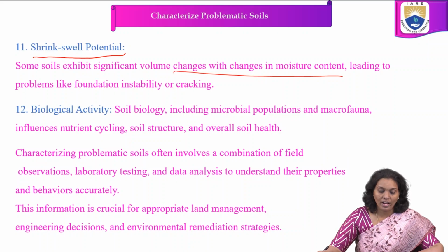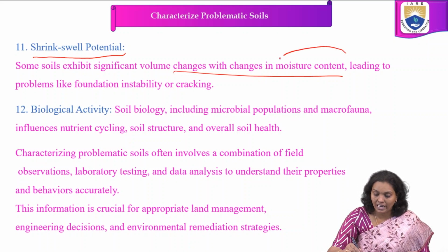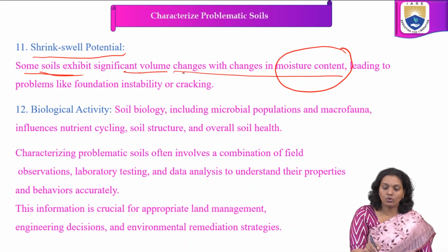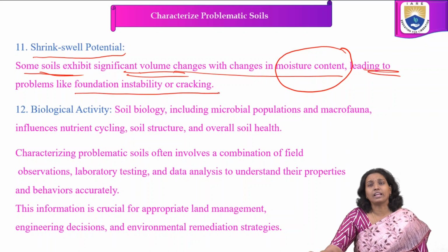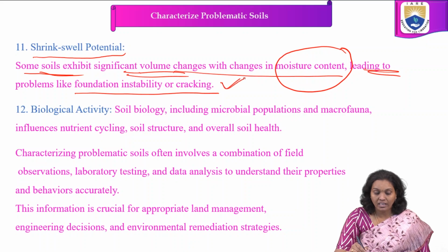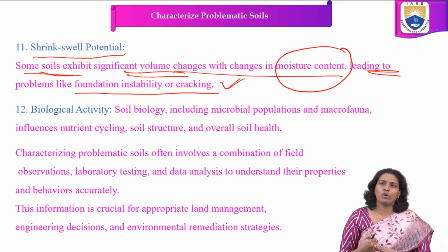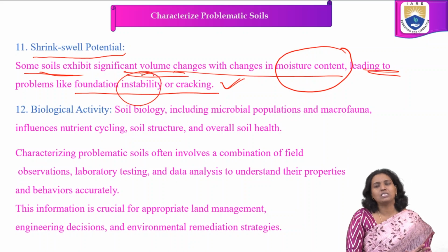Some soils exhibit significant volume changes with changes in moisture content. Because of the moisture content changes, the volume of the soil is going to change, leading to foundation instability or cracking. To prevent this, we have to understand this problem. Shrink-swell potential leads to problems like foundation instability and cracking, and it sometimes affects the total construction.